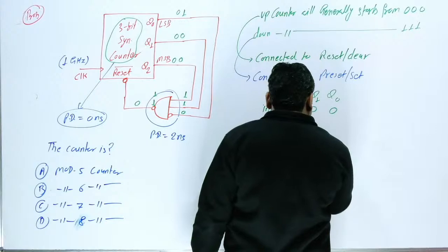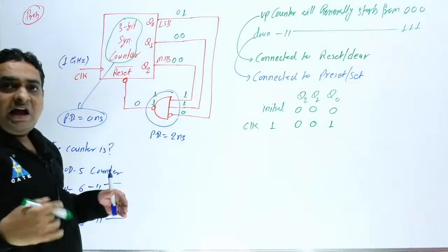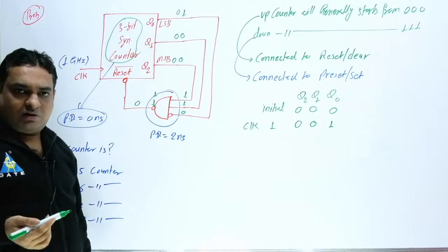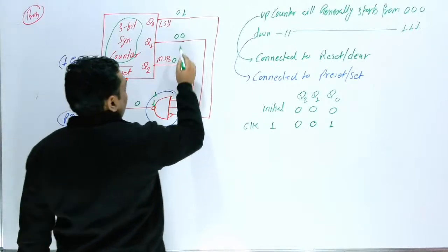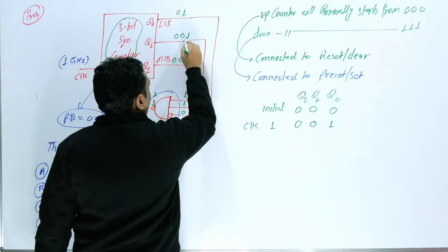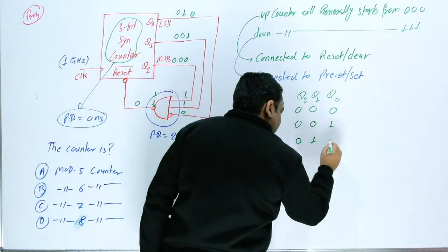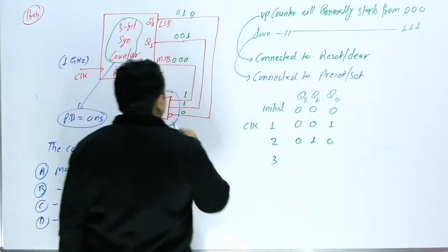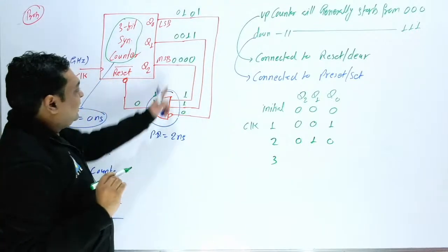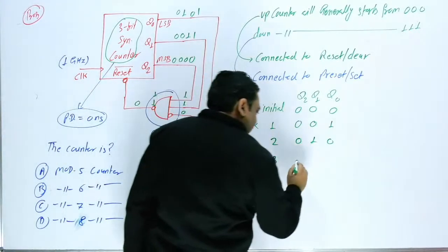When you apply the first clock, you get output 0 0 1. Right now I am assuming there is no delay, then I will consider the delay. So 0 0 1 is not the reset condition. Then clock 2 gives 0 1 0, again not reset. Then clock 3 gives 0 1 1, again this is 0, this is 1, this is 1, not the same.